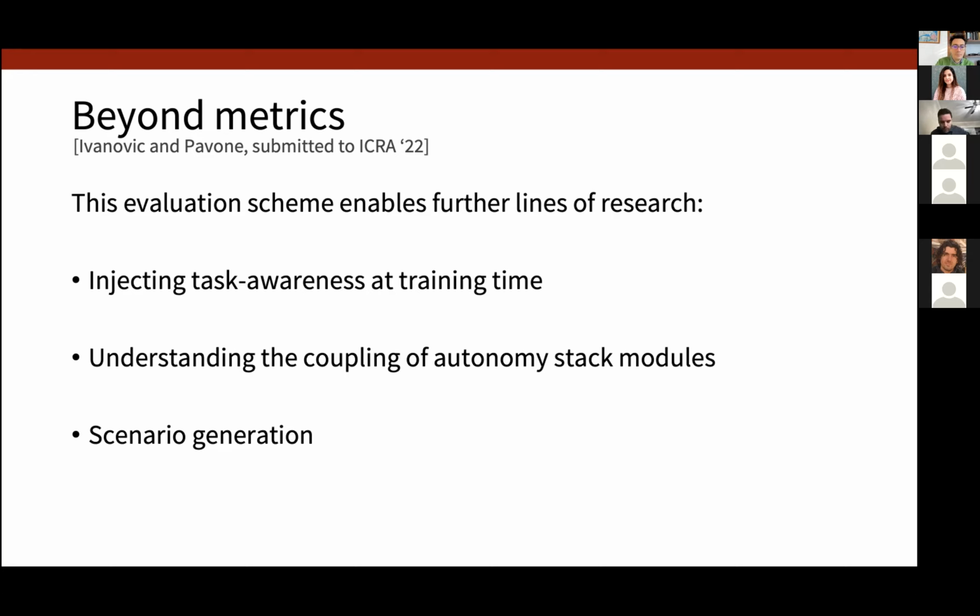And then finally, with scenario generation, once you have this measure of the ego vehicle's sensitivity to other agents, you can, for example, inject adversarial disturbances into existing scenarios. If we wanted to change an agent's behavior in order to affect the ego vehicle's planning, this method is able to tell you that this agent would yield the maximum difference to the ego vehicle's planning, and it would even tell you in what way, because if you take a gradient step, you're taking a gradient step that is directly making the ego vehicle's planning costs worse. And so you could directly affect the ego vehicle's planning in the worst way, so to speak.